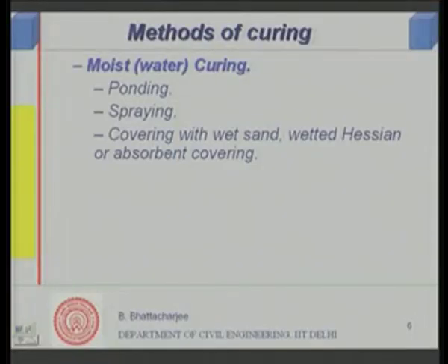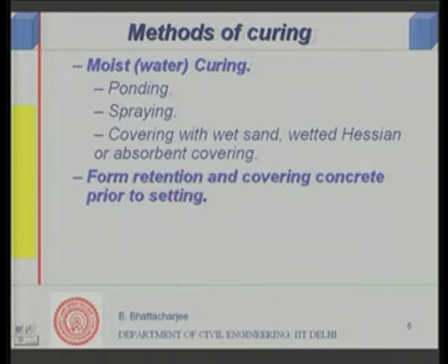In such a situation you can do something else, you can cover it with wet sand. If the sand is drying off, spray water again. Sand will hold on to the water for a longer period of time, and periodically you go on wetting that sand. Then there is wetted Hessian or absorbent covering. You put some sort of gunny bags, for example old jute gunny bags or similar, which can absorb the water and keep the water in position, some jute or cotton waste or Hessian. The old gunny bags were used very often.